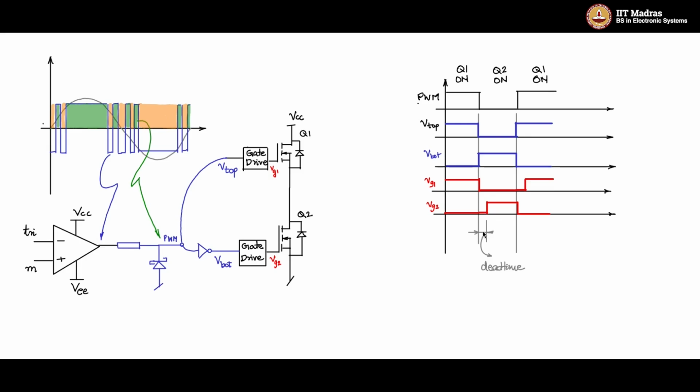This we have to obtain by some circuitry. So where will that circuitry come? Just before the gate drive circuitry, here I want to insert this red shaded pre-block. This pre-block is the dead time circuit block, and we will draw the circuit for generating the dead time such that we get VG1 and VG2 waveforms like this, starting from this PWM waveform, here.